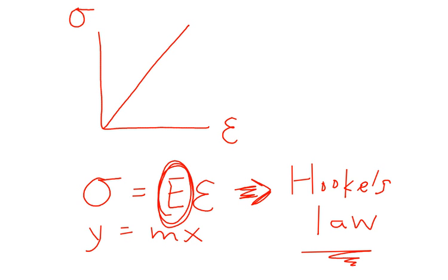Okay. And what are some typical values? If you look in that table, in the SI system, Young's moduli are on the order of gigapascals. They're huge, right? Gigapascal, if you remember, is 10 to the 9th pascals. And in the US system, we're talking about 10 to the 6 psi. So Young's modulus is usually pretty big, right?